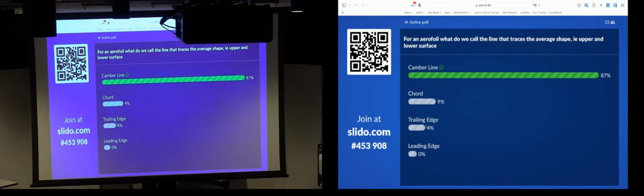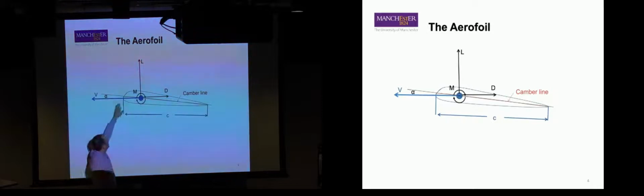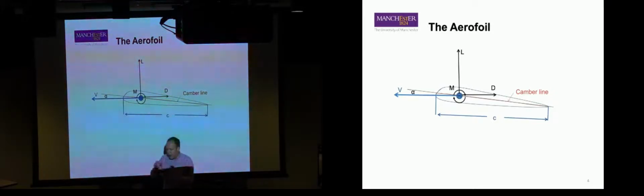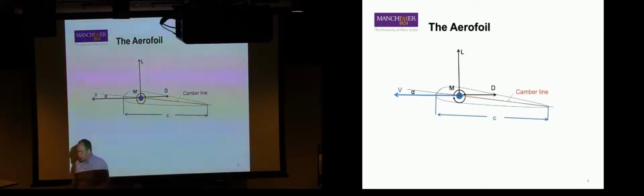If we go back to our airfoil, we have our leading edge here, our trailing edge here, and by definition, the leading edge is the first part of the airfoil that the flow sees, and the trailing edge is the last. The pure linear distance between them is our chord, which we use that little c symbol for. Now you may see a little c bar or a little c hat, and those are things like mean aerodynamic chord and mean structural chord. But for an airfoil, that's the same thing, so it doesn't matter.